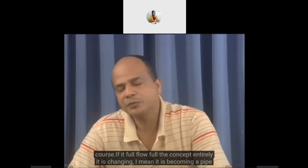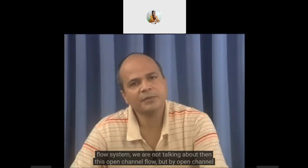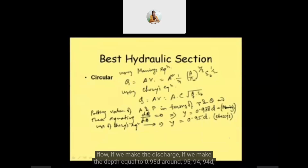Of course, if it flows full, the concept entirely changes. It is becoming a pipe flow system, and we are not talking about open channel flow then. But by open channel flow, if we make the depth around 0.95 d, then we get maximum discharge, and we should not carry the depth beyond that limit.